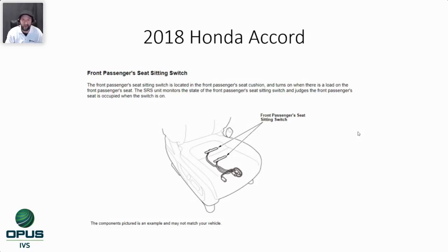It's a switch input. They have two little bars that come across there. They are nothing more than contacts that have a predetermined amount of gel inside, so that as you press down, it takes a certain amount of weight on top of the seat sitting switch to determine that there's someone actually there. Someone's actually actively in the seat.